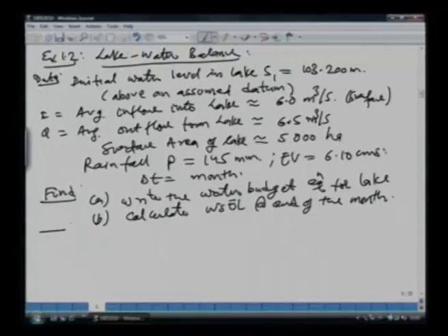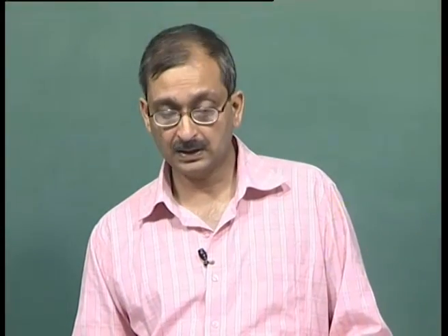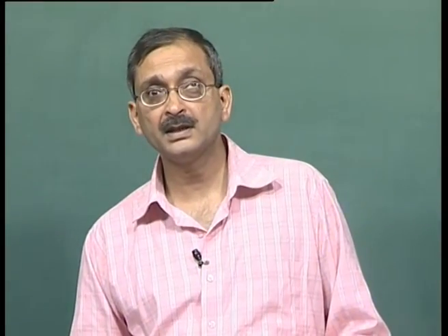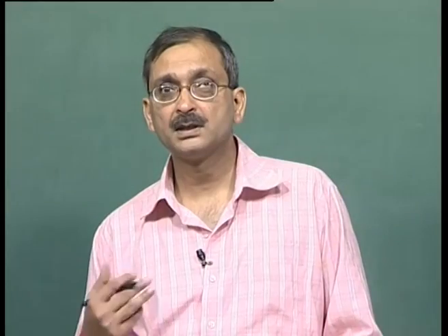So, to solve this problem, we just need to write the continuity equation, that is inflow minus outflow is equal to change in storage. Inflow components are given to us, and there are two inflow components in this case. One is the surface inflow and the other is the precipitation, and as far as the outflows are concerned, there is surface outflow Q and also the evaporation.